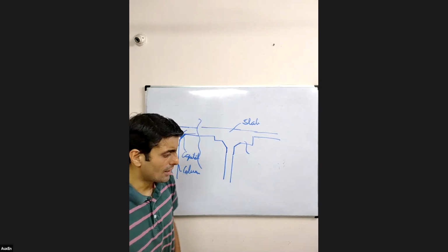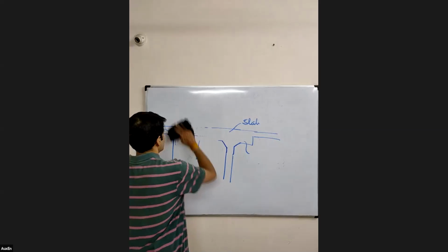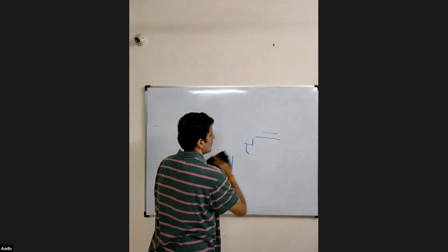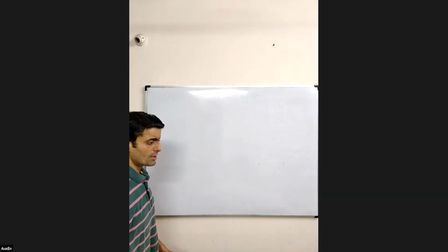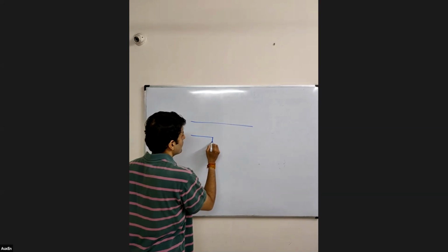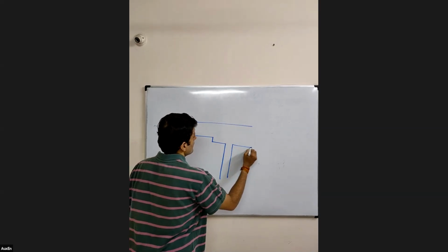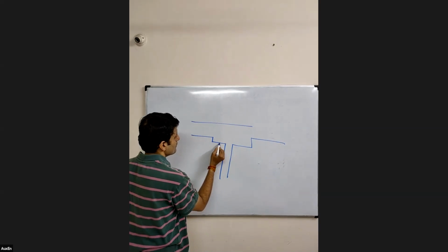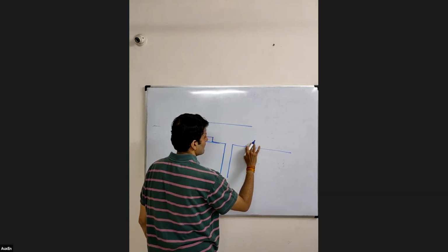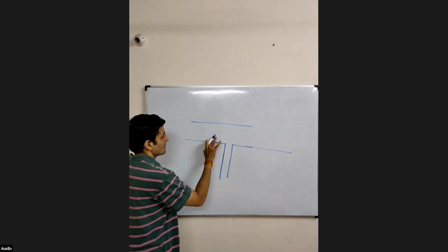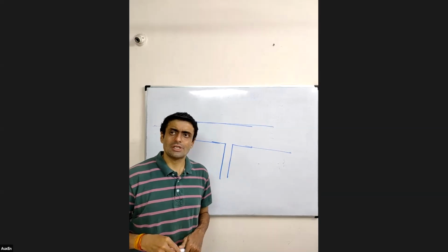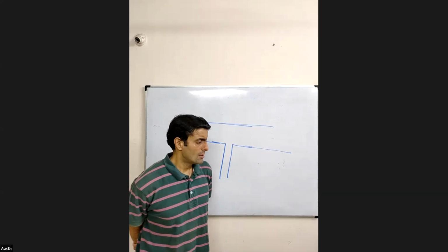That we increase the slab thickness in such a way that it takes care of all the punching that is going to develop. Okay. So instead of, let's say, providing a slab where we were going to provide drops and slab, instead of this, what do we do? We straight away provide one thick slab, like this, so that it is able to resist all the punching that can come.